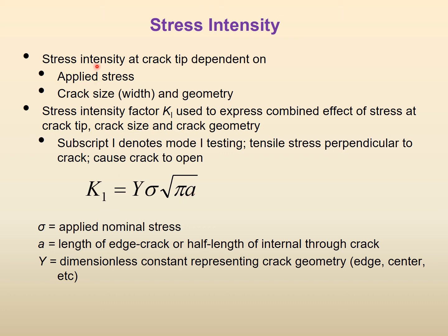So stress intensity at the crack tip is dependent on the applied stress, it is dependent on the crack size, and it is dependent on the geometry of the crack, right? Whether it is an edge crack, whether it is a center crack, whether the crack is elliptical in nature, whether the crack is circular in nature, all those things come inside this crack size and crack geometry.